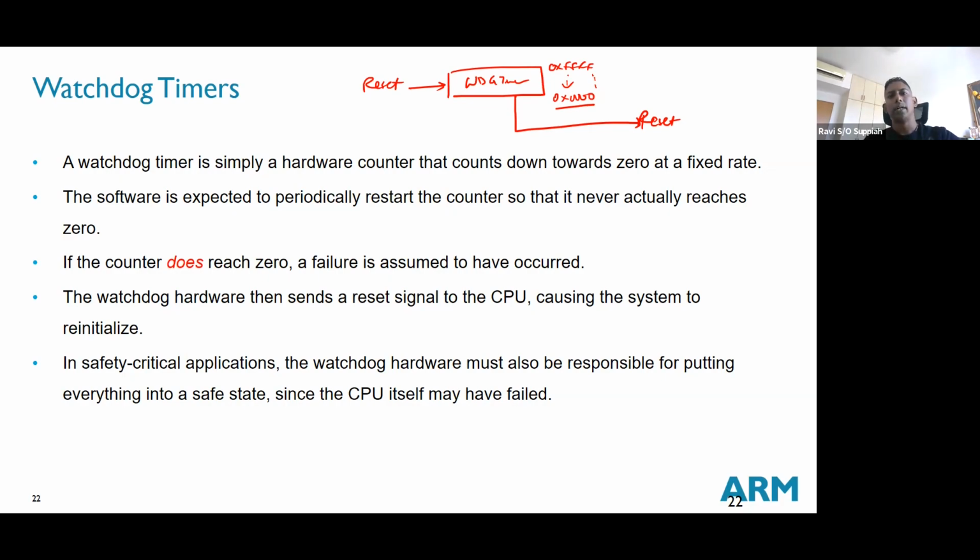Generally we do not really use it that much. But if you're talking about a final product that you're going to implement or market, it's good to look into this watchdog timer concept, so that in the event that something happens, it is able to reboot and at least go back to a proper state.